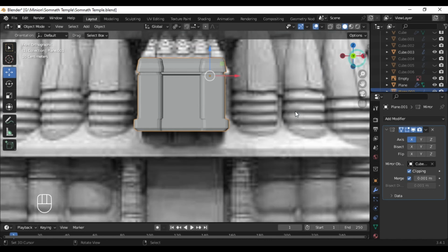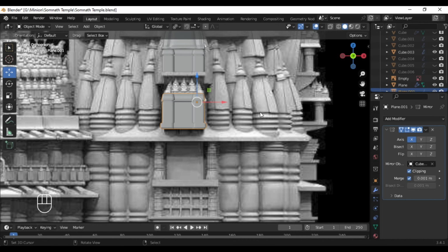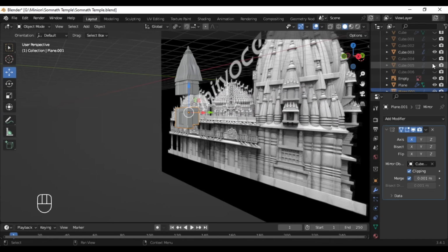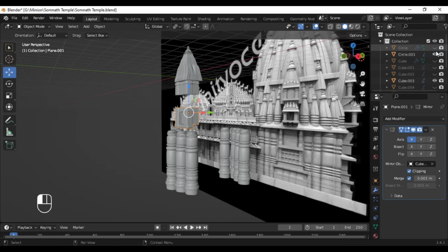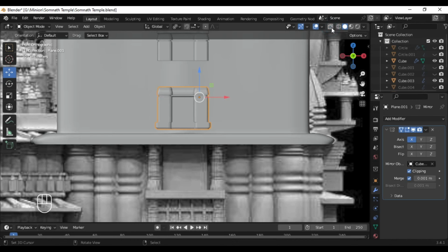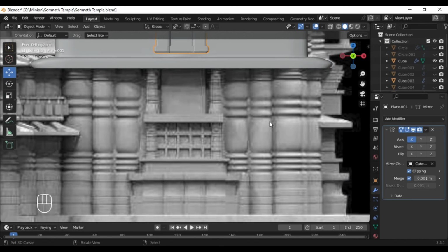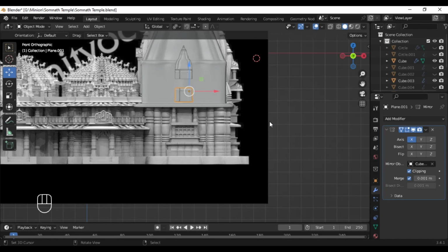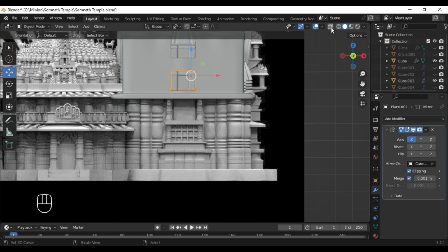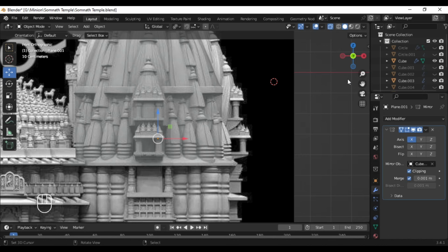So here you can see I have been struggling with filling the gaps. The best solution was to extrude that uppermost portion instead of filling those gaps with different numbers of vertices, which would be a very terrible thing. So the solution would be to just extrude it along the z-axis and leave the gap, and not actually fill the gap. That will be the best solution.